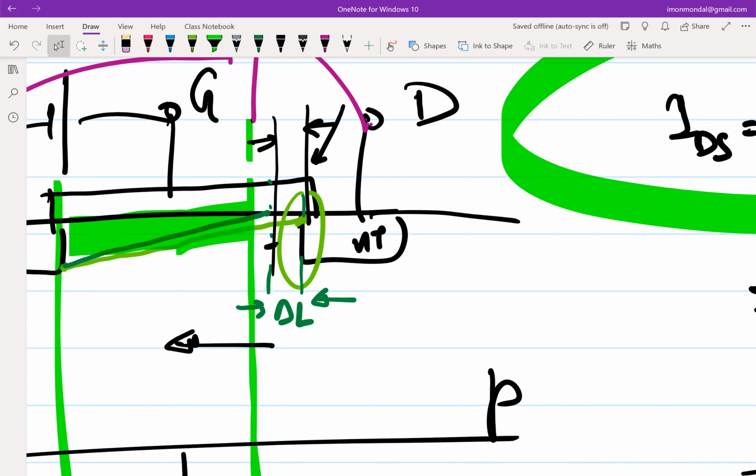So in a PN junction, in the depletion region, when you had electrons and holes getting generated, they were sucked into the P and the N side, which was giving rise to some reverse saturation current in a PN junction, right? So the concept is similar here, just that the charges are not getting generated by thermal effects. The charges are provided by an adjacent channel, a channel which is just next to that pinch off region. Since charges are available very close to the channel and you have electric field penetrating that channel, the charges are getting sucked in.